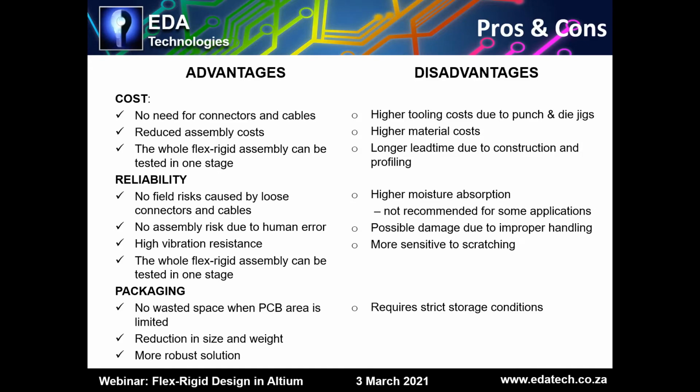It can withstand much better vibration. So if you're doing avionics products, this is a much better choice. And then also the packaging, you're using a lot less space on the board. You don't need connectors and bulky board-to-board connectors. So there's lots of advantages to flex rigid PCBs.